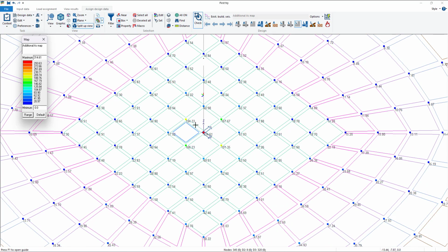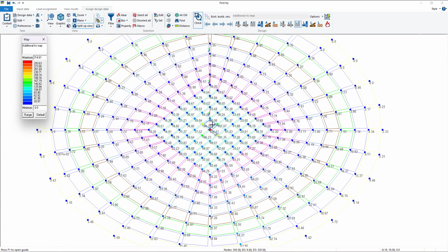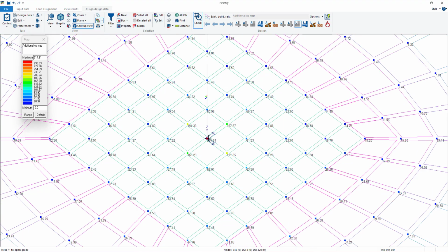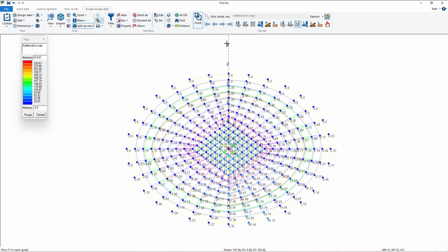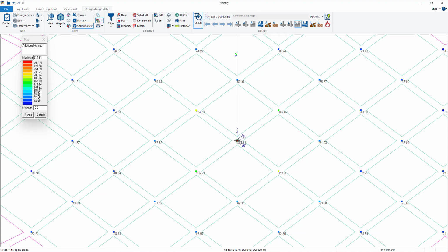Well, here it is required, of course, because we have an element that weighs a lot, that, how to say, its gravity is concentrating all its self-weight on the same node. So this is kind of an error during the modelling. We should never have an element big like this reaching only one node.